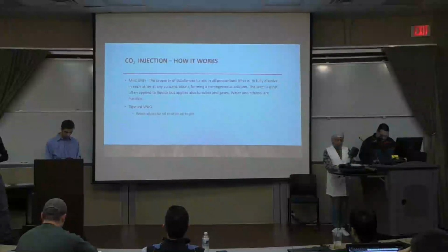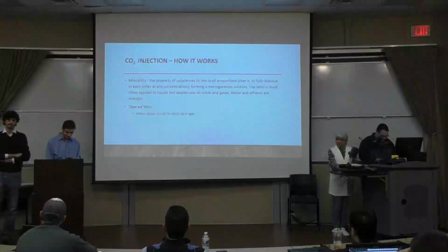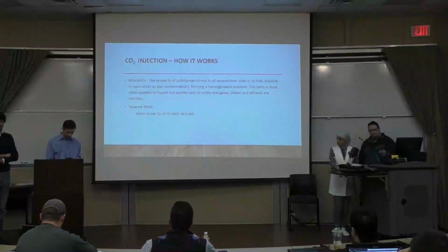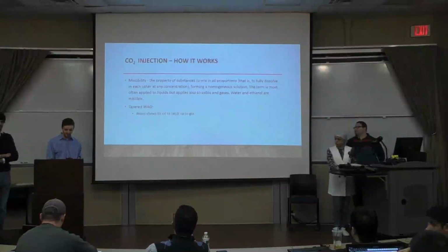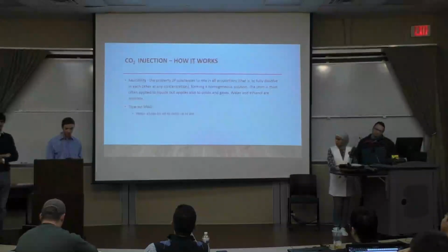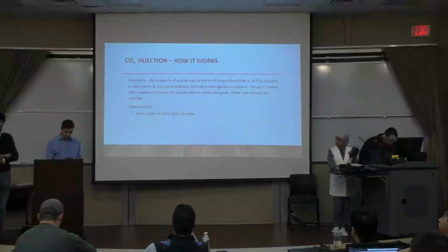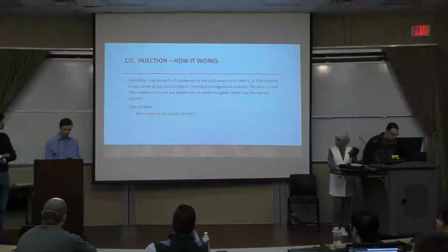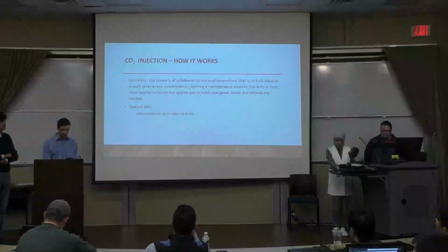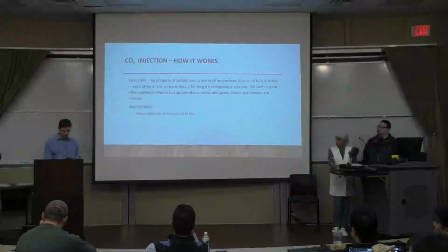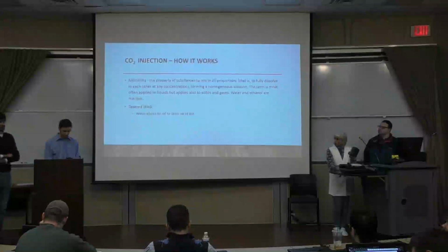Mixing allows the CO2 to displace oil from the pore spaces, and that pushes it towards the producing well. And if the reservoir pressure is above the minimum miscible pressure, then theoretically recoveries could be as high as 90%. The taper WAG is like the conventional water alternating gas, but it gradually reduces the injected CO2 volume relative to the water volume. This improves the efficiency of the flood, as well as prevents early breakthrough.